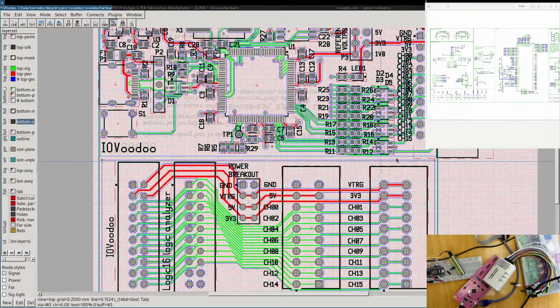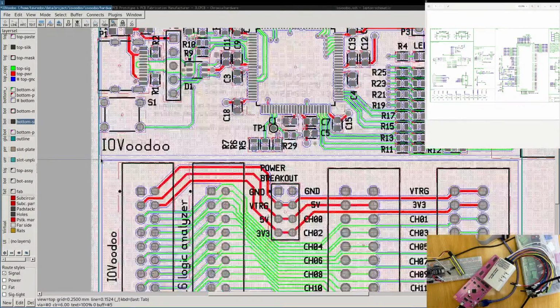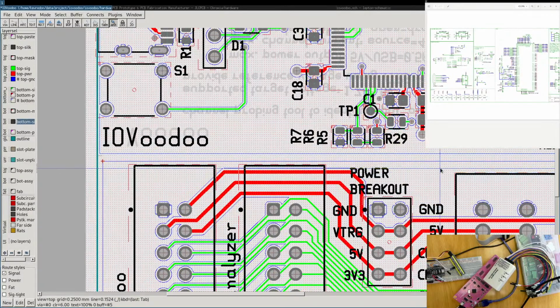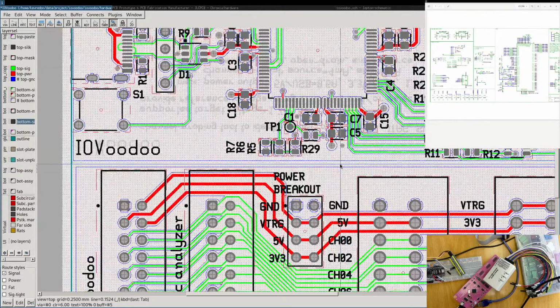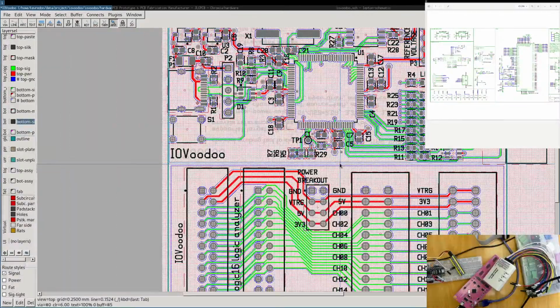It's just this connects here. It's a two-part design, like this. But ideally, you would completely route them separately. So you have two different designs, what they call designs on the manufacturing side, or you have one design with two boards, and then you add a routing here, like you would make for a panel.